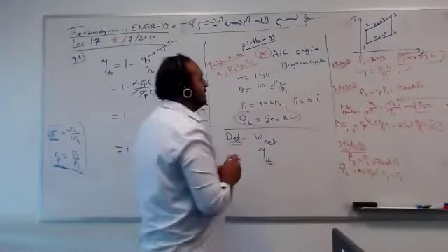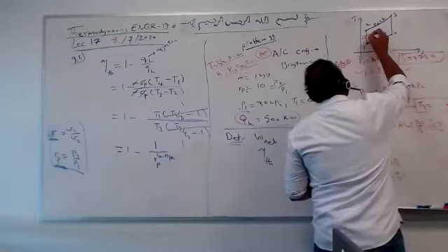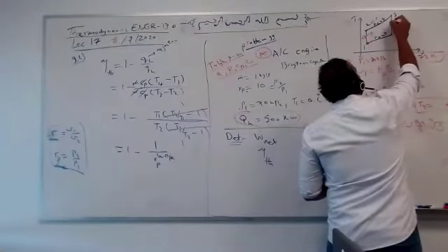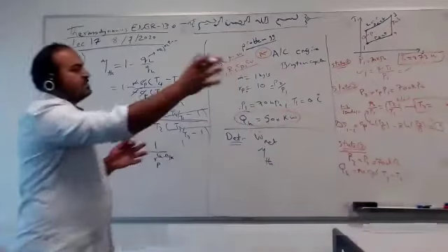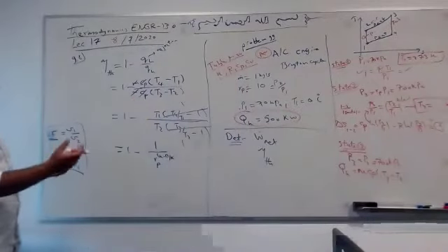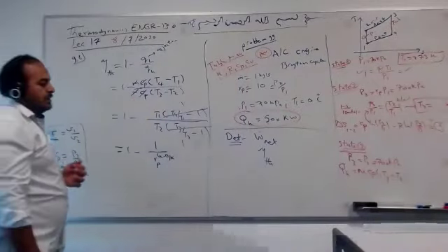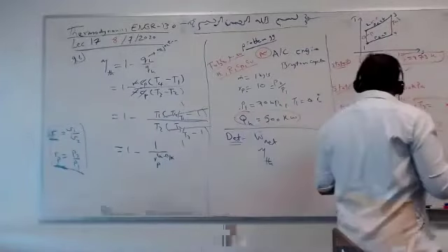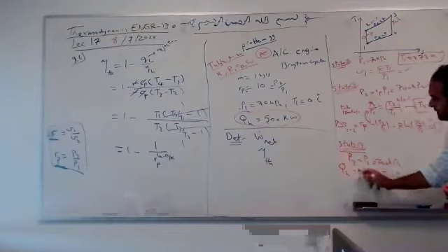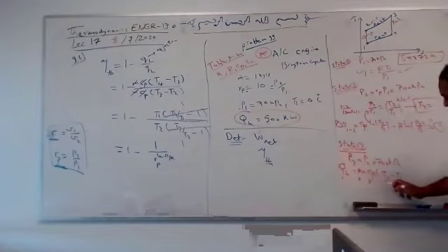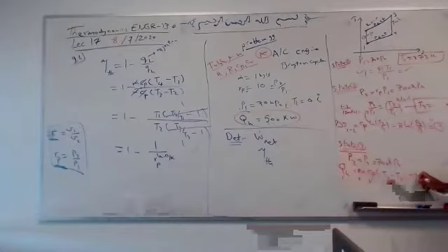This is the combustion chamber. We have the compressor, combustion chamber, turbine, and rejection to the ambient. We don't have a component for rejection, we just dump the air and get fresh air, so it looks like a cycle. So we have Cp, m dot given, Q high given, and T2 from the isentropic process between 1 and 2. We can get T3, box it.